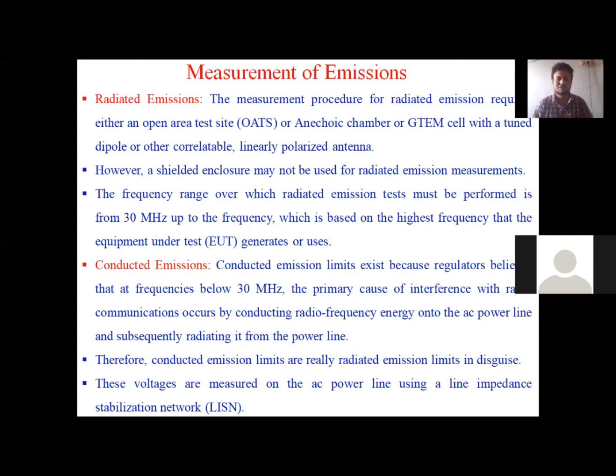So testing of this emission generated by antennas is a very costly thing. So how to measure the emission generated by your antennas? The operating frequency must start from 30 megahertz, and the highest frequency should be the highest operating frequency of your device or antenna under test.